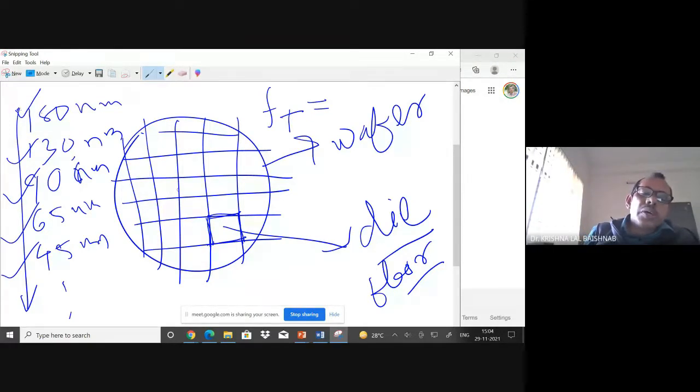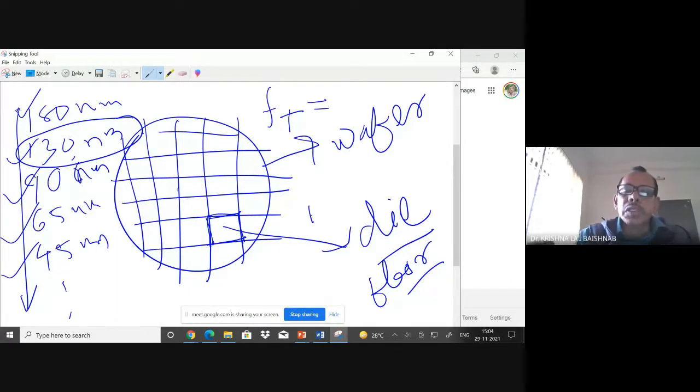See, that's the challenge. Today, what we see is mobile communication, everybody has a mobile, even fishermen. This is basically from 130 nanometer onwards. Before that, BJT was basically used for RF applications. MOS was not suitable before 130 nanometer for RF applications. Point to be noted: RF applications start at 130 nanometer and downwards.